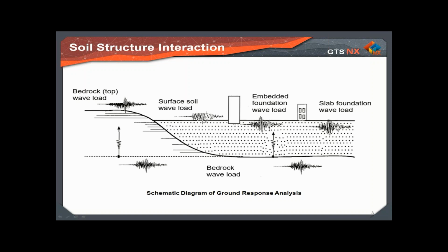The ground displacement, in turn, is largely influenced by the dynamic properties of the ground and its modeling method. The ground exhibits a complete nonlinear behavior depending on the strains developed in the ground due to the dynamic load. It is therefore important to closely examine the nonlinearity of the ground relative to strains.